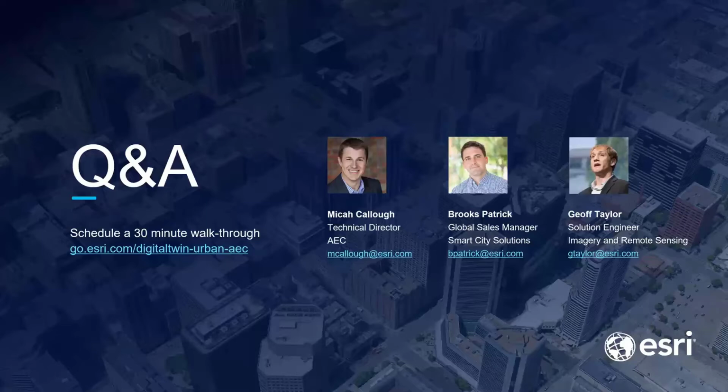So the question that we had was, I have my classified LiDAR now that I've classified in ArcGIS Pro or another solution. I want to share it. Well, in ArcGIS Pro, you can select the visual of just seeing the classified point cloud first before you export it, and run a tool called Share Point Cloud Scene Layer Package, or Create Point Cloud Scene Layer Package. And then you can generate that scene layer package, which is multidimensional, so it loads quickly on the web. And people inside of your organization, on your enterprise, or outside of it can all access and use that. And the size is very small in those.